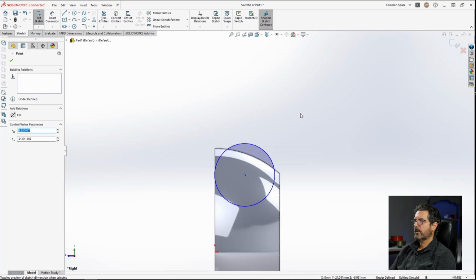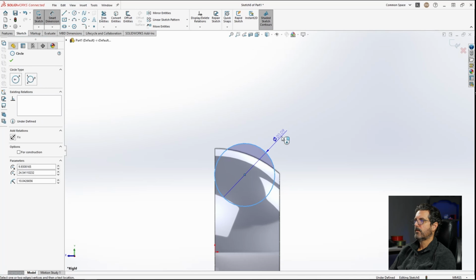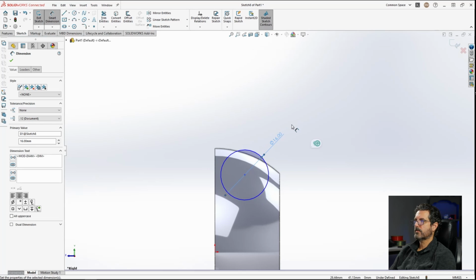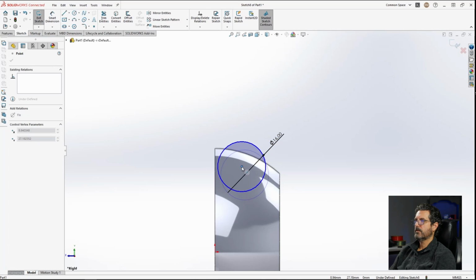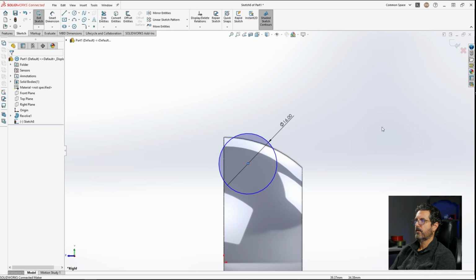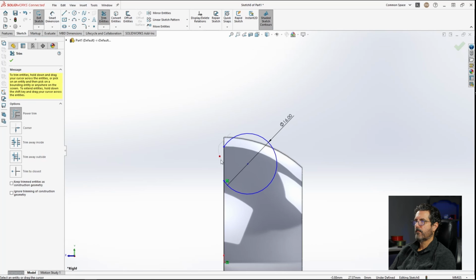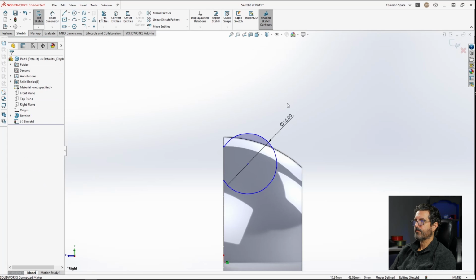And I think we're going to go, let's try 16 millimeter circle. And we're just going to make it stick up just a little bit here. About there. Okay, now I just want everything inside here. I don't want to cut it at that because that curves downward. So let's go ahead and convert this to entities and trim this thing up. Okay, now we have a solid item.